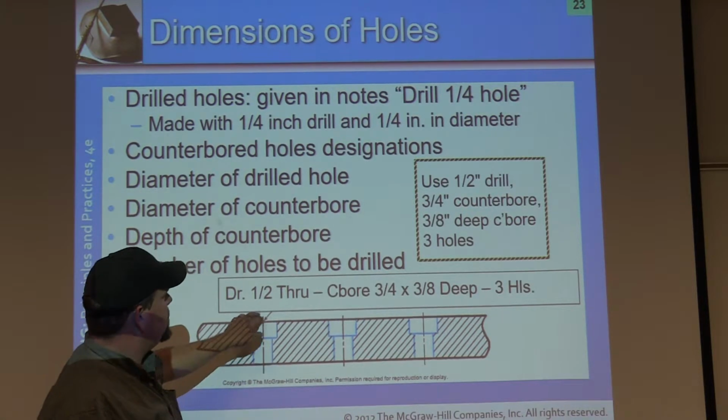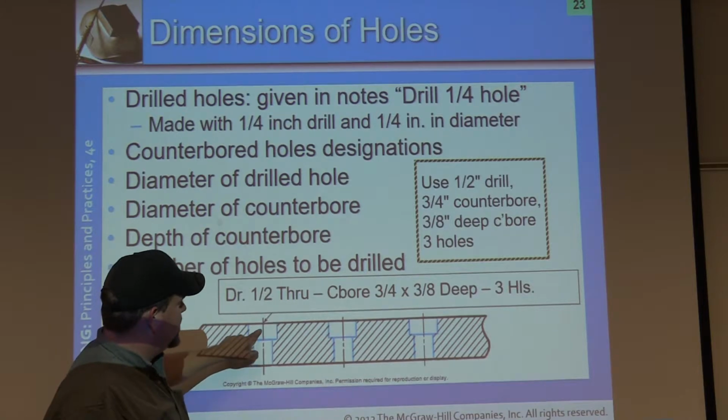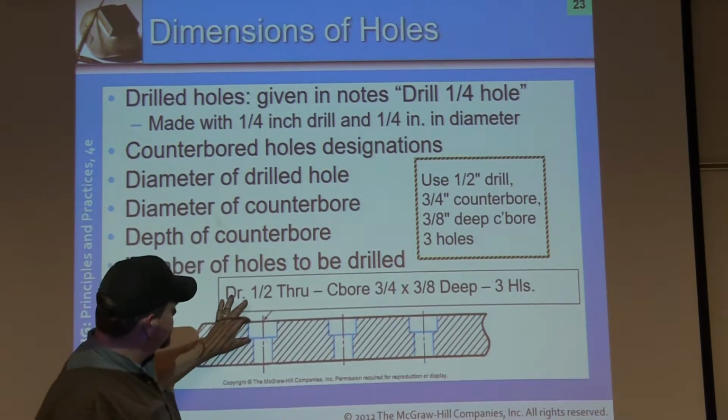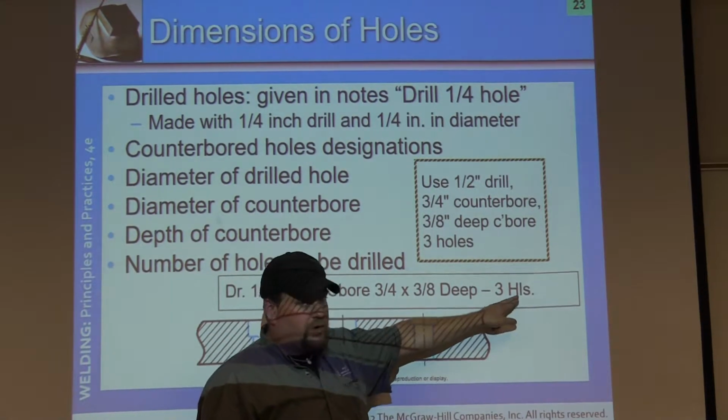Okay? Your counterbore is 3/4 of an inch wide, so that's in your diameter, by 3/8 of an inch deep. Okay? And as you see, typical for all three holes.